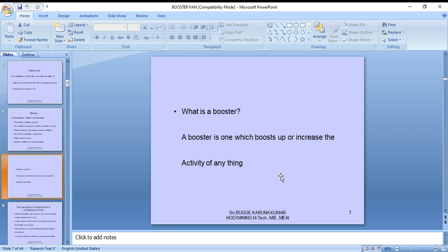A booster is sometimes used for ventilation in certain districts. They increase the quantity by increasing the pressure, causing flow, and the size of the booster fan can be calculated for any quantity depending upon the requirement. Increasing the quantity in the booster district increases the total quantity passing through the mine, which results in greater pressure losses in the shaft and the trunk airway, thus reducing the pressure across the splits.